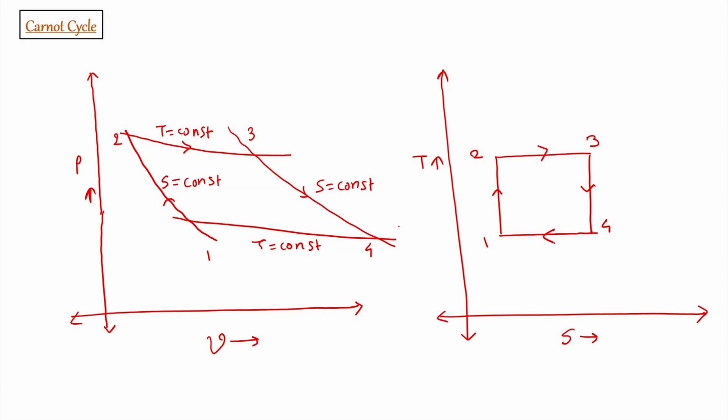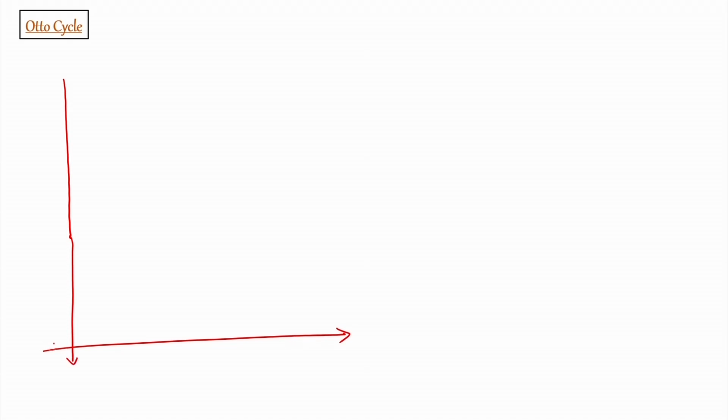Now, this cycle is an ideal cycle where all processes are reversible. Now, let us move towards the next cycle, which is Otto cycle. We are interested to see this specific part in the overview of thermodynamics because these cycles constitute the engines which are the complementary engines towards our gas turbine. So, Otto cycle is basically leading to SI engine, which is a spark ignition engine, or in our case we call it a petrol engine.